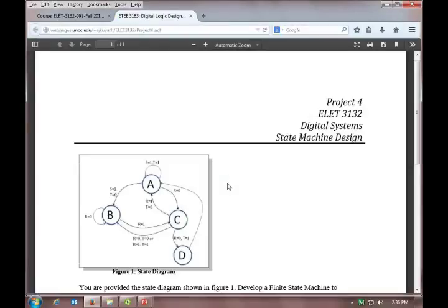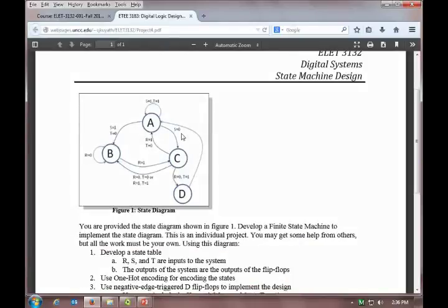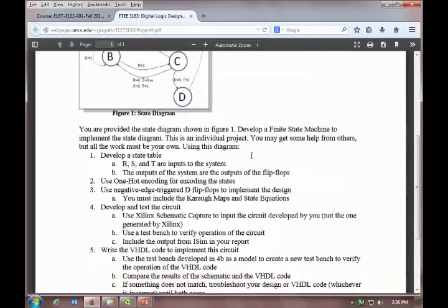I showed it to you, but I want to make this very clear, and this is the second time I've said it. This S equals 0 is with this line. It's associated with the transition from A to C. There is no input associated with the transition from D to A. So that is unconditional. When you get to D, you go straight to A. All right? I don't want anybody telling me they never knew that, because it'll be too long, too bad. I said it a couple times.